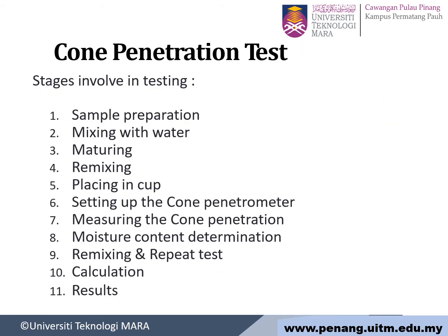Okay, this is the stages involved in testing. First is you have to do the sample preparation, mixing with water, maturing, remixing, placing in a cup, setting up the cone penetrometer, measuring the cone penetration, moisture content determination, remixing and repeat test, calculation and result. This is the stages involved.